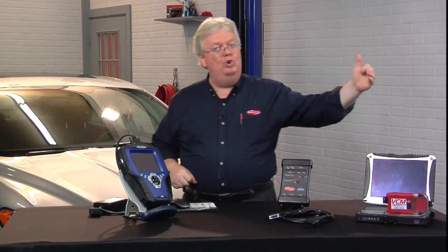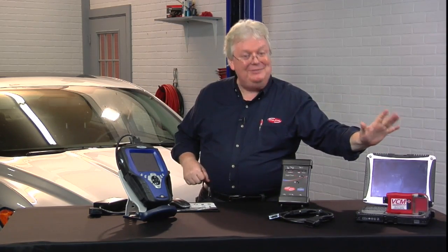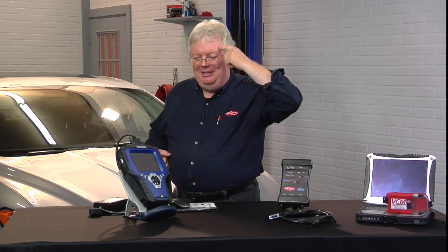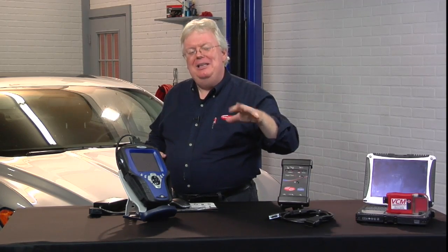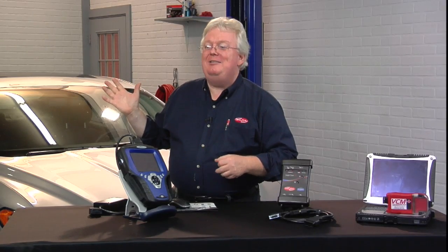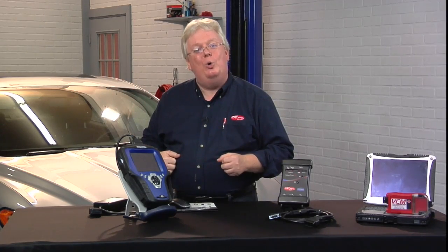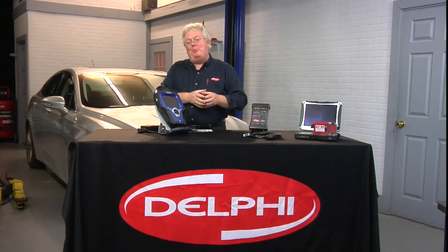So I've seen on different scanners that are not true OE factory tools, and occasionally on them too, but mainly on the aftermarket scan tools, I've seen glow plug PIDs on a gas engine. Scratching my head going, nah, it's not there. So this stuff happens, and it can happen from the lowest little generic scanner up to the biggest one. The bigger ones, usually they got more budget and they fix those software holes, and the bigger holes get filled pretty quick.